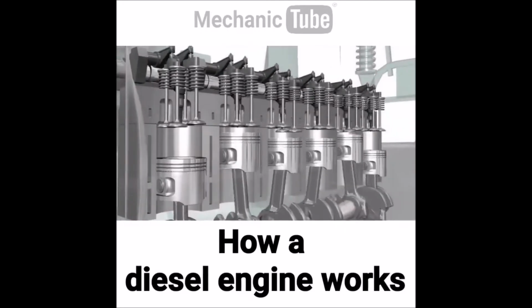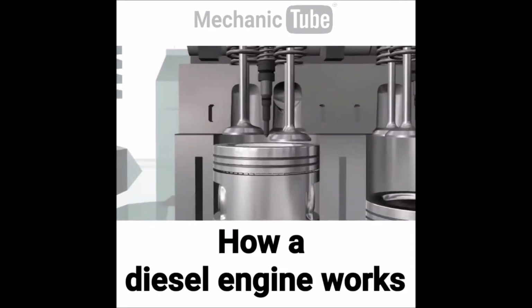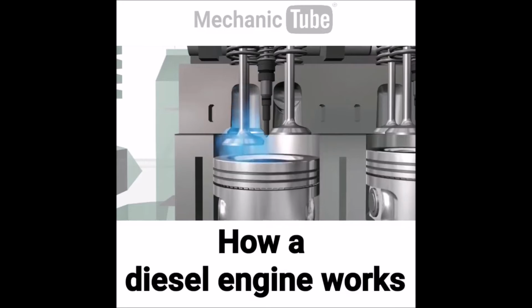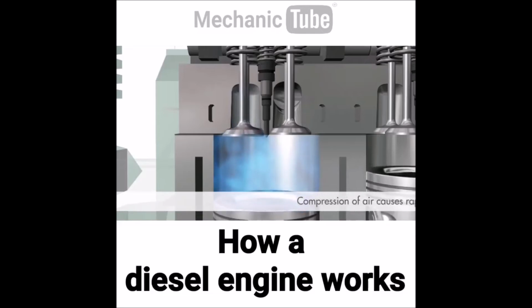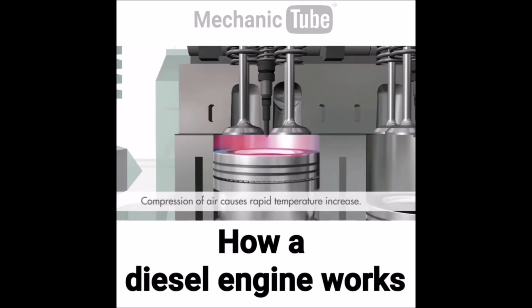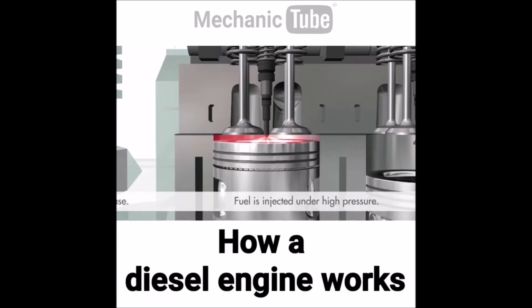In diesel engines, the operating cycle starts with clean air being drawn into the cylinder, not a fuel-air mixture as in a conventional gasoline engine. The motion of the piston compresses the air, heating it to a high temperature. When the piston nears the top of the cylinder, fuel is injected under high pressure through a number of precisely machined holes in the tip of the fuel injector.